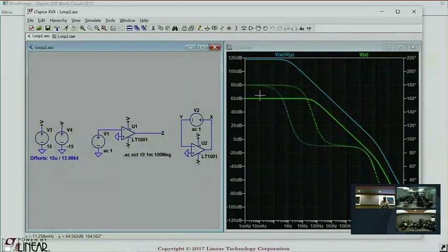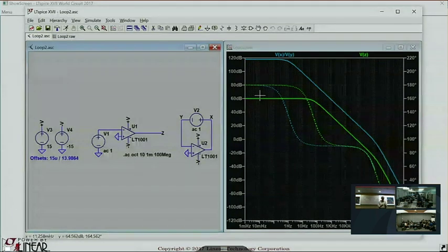if you have a feedback loop, when you cut the feedback loop, the circuit doesn't work anymore. So to measure the transfer function, you have to solve the stability first. Then you can measure the open loop transfer function, and then you can say whether or not it's stable. This doesn't bode well for a useful theory. The theory is supposed to help you solve stability, but the process for applying frequency domain analysis is: first you solve the problem, then you get your data, then you can analyze whether or not your problem is solved. That's a problem.